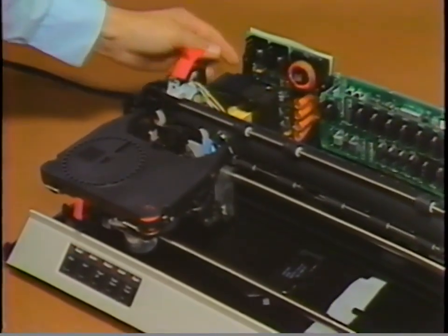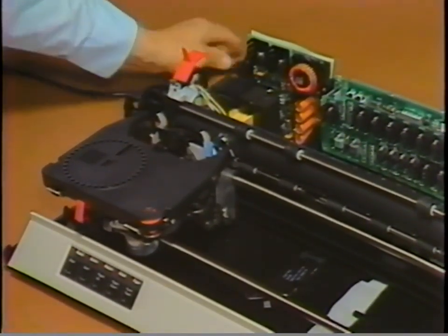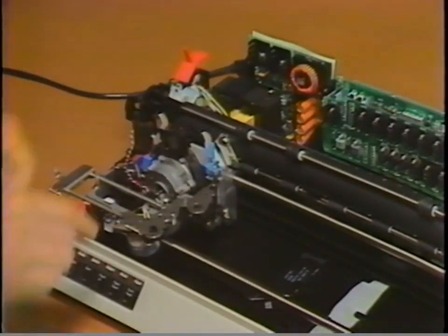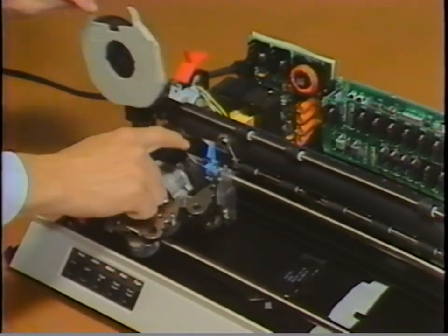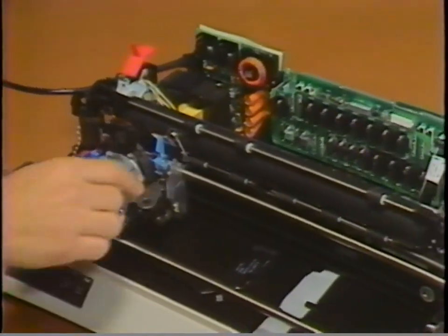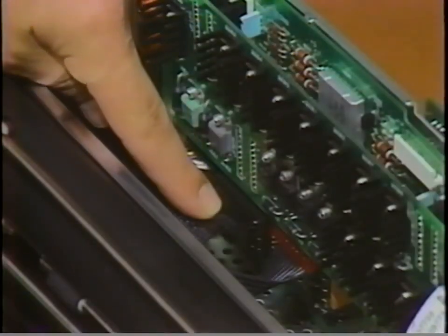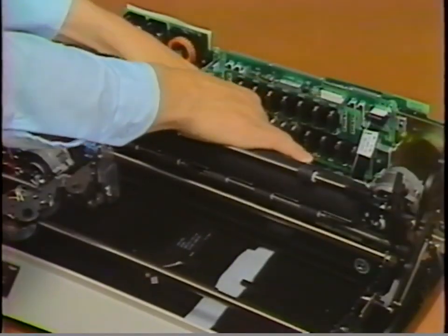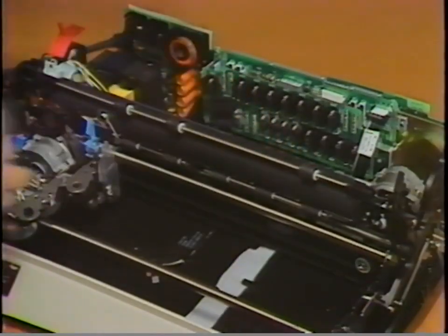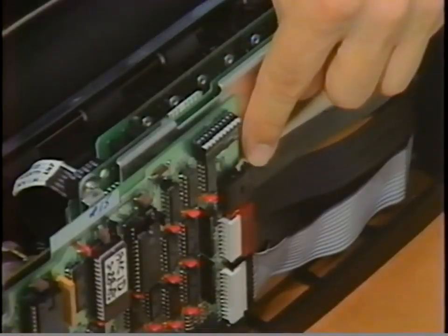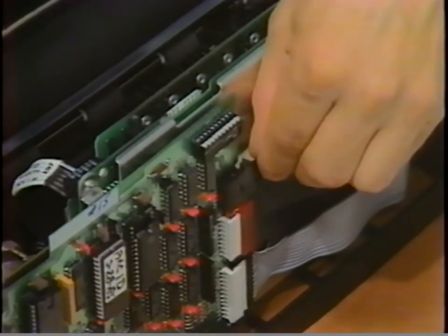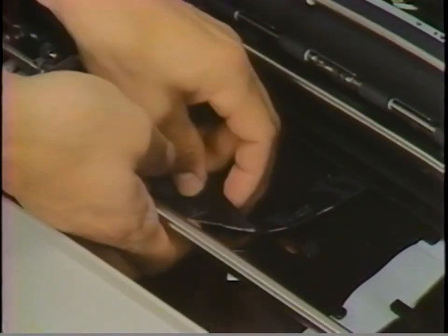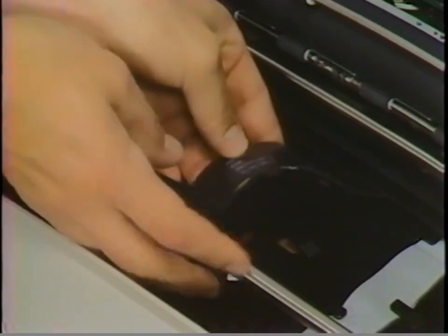To remove the carrier, start by turning the machine off and removing the line cord. Next, remove the ribbon and print wheel. Disconnect the carrier cable from the J4P connector on the printer board and the end of ribbon cable J1 from the function board. Work the cables out from under the frame and the clips in the base of the machine.